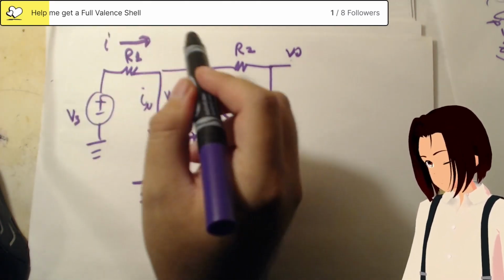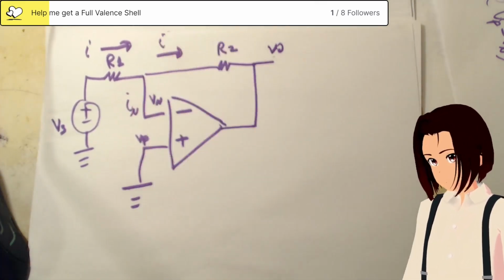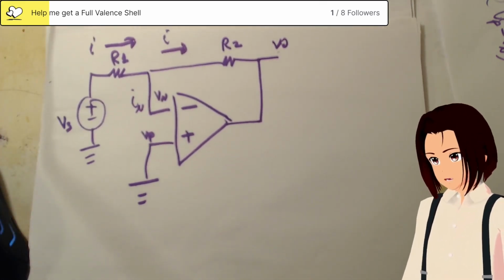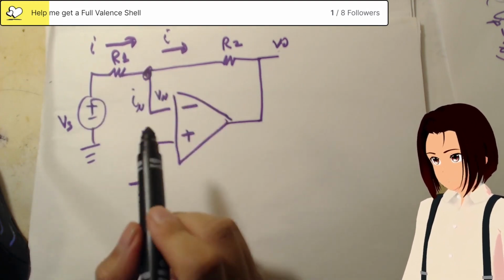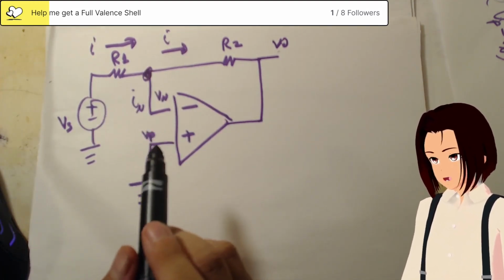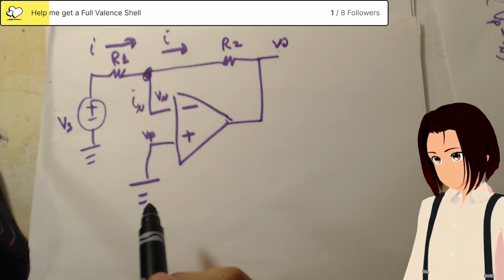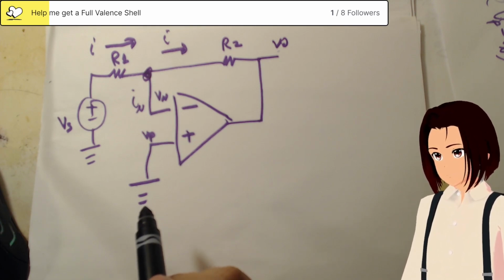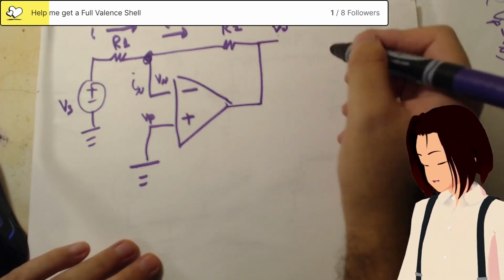It doesn't matter, the voltage is still probed there. It has to be 0 voltage at that point, right? Yes, the potential right at this node is an equipotential of 0 volts. So then the voltage at V0 is equal to the voltage across R2. The voltage drop across R2 equals the voltage at V0. Yes, that's true.